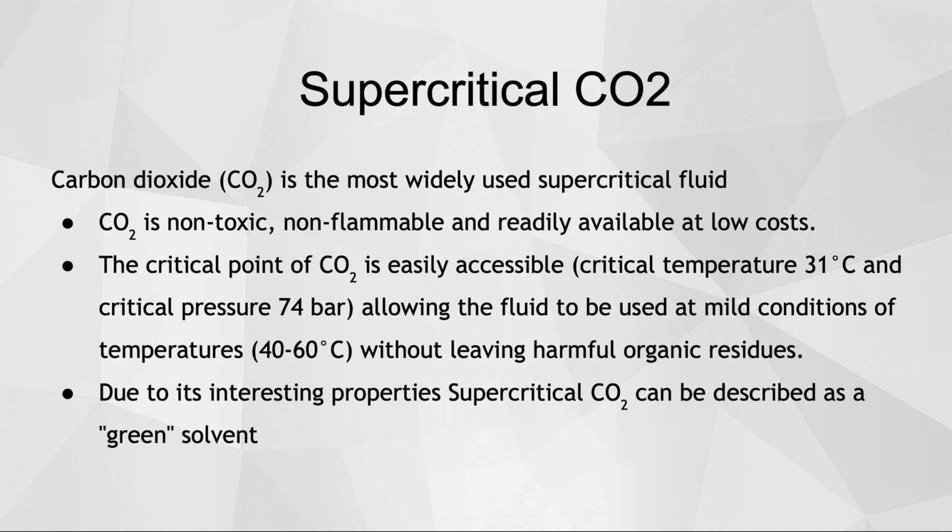The critical point is also easily accessible, being 31 degrees Celsius and 24 bars in pressure. This allows the fluid to be used at mild temperatures of 40 to 60 degrees Celsius without leaving harmful organic residues. Due to its interesting properties, supercritical CO2 can be described as a green solvent, meaning it's very environmentally friendly.